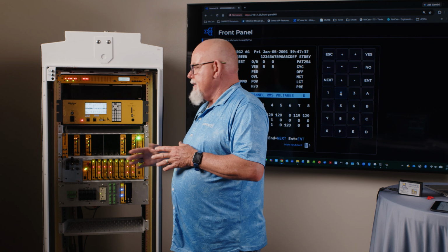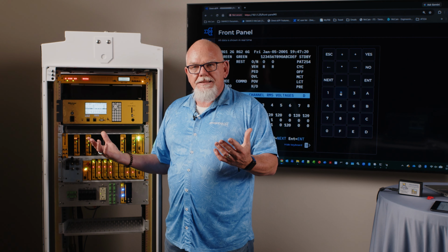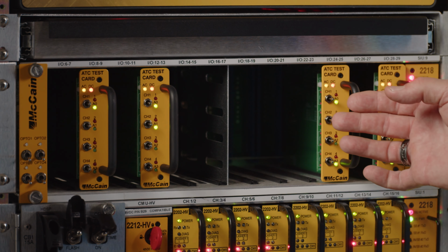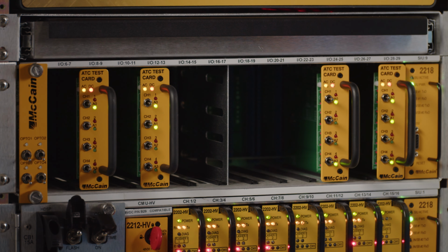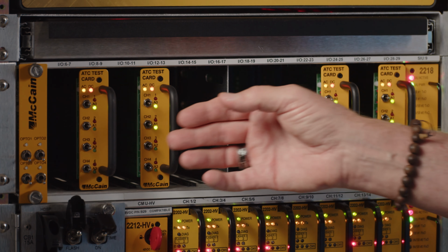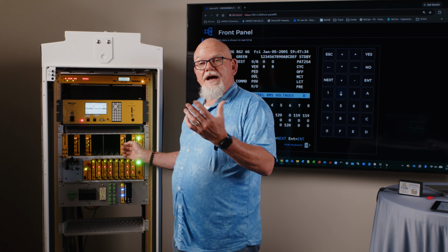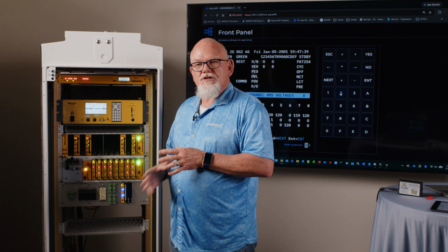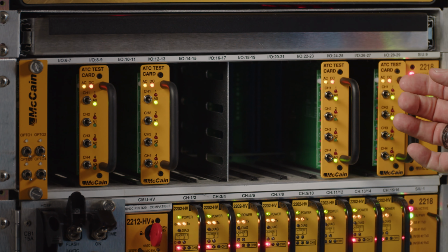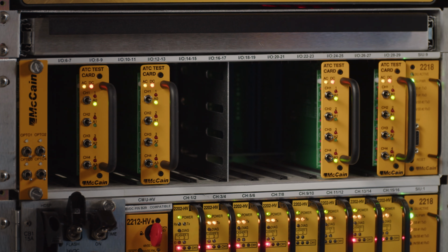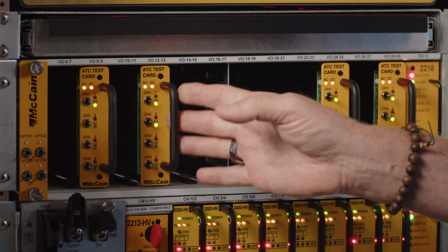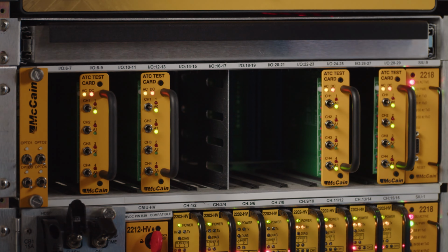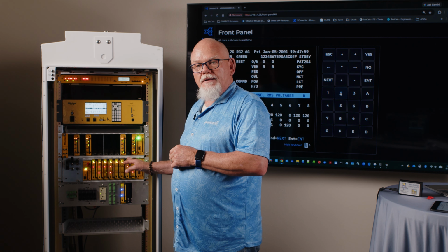The next thing we're looking at is our input file. The input file is basically a detector rack. This is a standard detector rack and uses standard detectors familiar to both Caltrans and NEMA users. So any detector you currently have would operate in this rack. We have up to 128 channels of detection. So as you need more detection, you just add additional racks. We also have a different model of detector racks that use high density detectors. The high density detectors are 4-channel detectors instead of 2-channel detectors, and we can actually get 48 channels of detection in one rack.